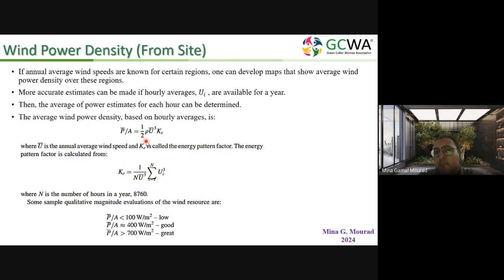We cannot visit a specific site and measure the wind velocity there with a probe for 1 day or 2 days or 1 week, and then determine the wind power density in 1 week or 1 month or 1 quarter. It is a fatal mistake. The readings should be taken over about 1 year, which can be calculated by hours, about 8,760 hours. We can take the readings from probes according to climatic conditions. The probes keep the same position and give readings for the site.